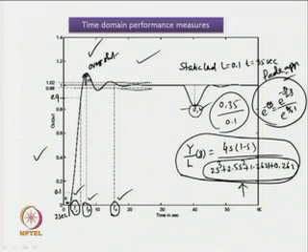So, this is one peak, and the magnitude of peak with reference to the reference input can be given as, suppose, P 1, and we have got another peak over here, P 2. So, the ratio between P 1 and P 2 gives us the decay ratio.